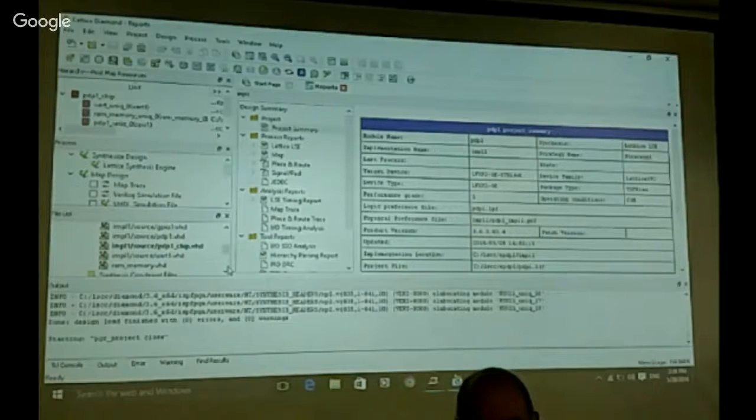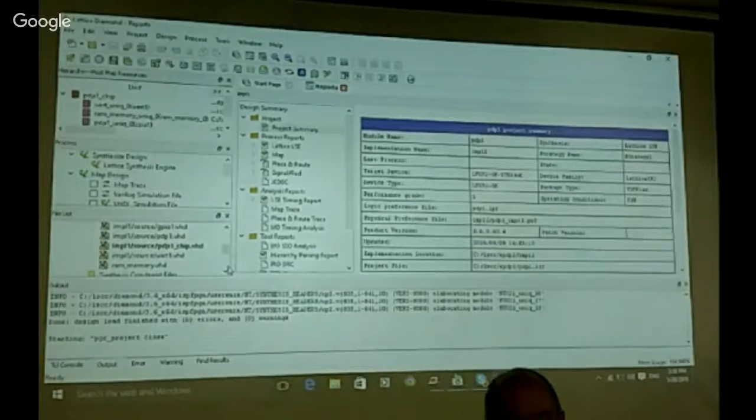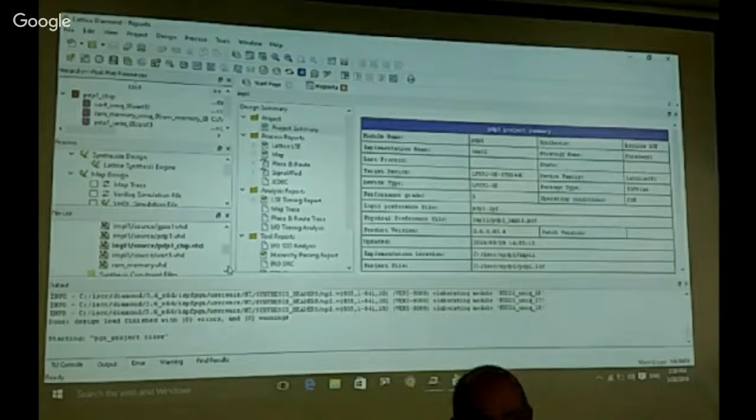It's called I/O because it tried to run I/O through that register besides doing the multiply. So the shifter is very sophisticated. You can shift up to 9 bits in one direction or the other. And you can combine the accumulator and I/O register and shift both as a 36-bit circular buffer.